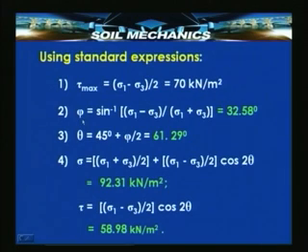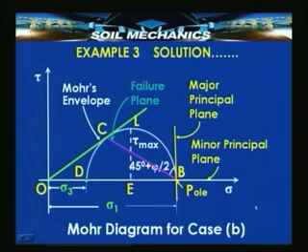The angle phi will be sine inverse of the quantities sigma 1 and sigma 3 which are known. Theta is again known from 45 degrees plus phi by 2. We can calculate sigma and tau from these quantities once again by using the same expressions. Thus, it is possible to compute the complete set of stresses either graphically or from rigorous computations.